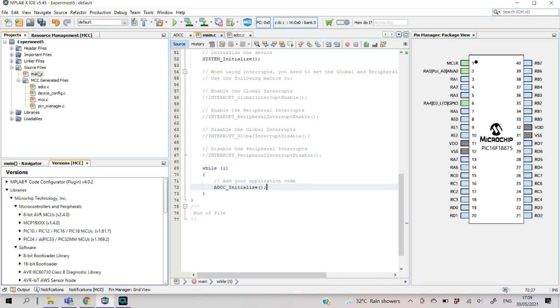We will set a threshold in order to turn on our LED. In this experiment, we will set the threshold to 512. It means that if it is less than 512 bits, the LED will set high. If anything goes above 512, the LED will turn off. By doing that, we will create an if else statement.